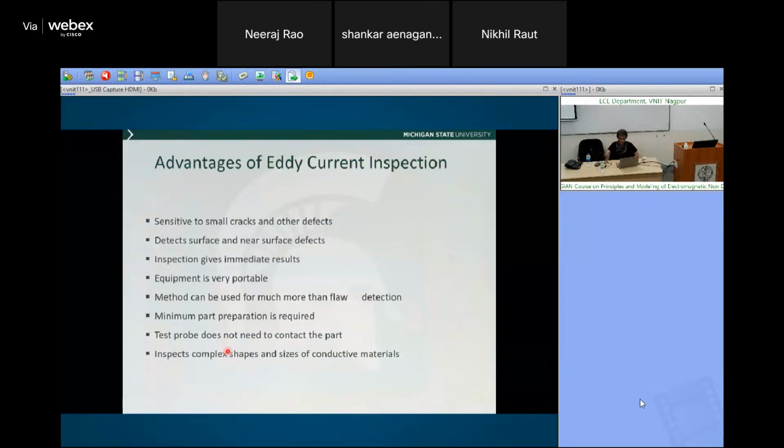The features are, we take 3 different frequencies, and at each frequency we look at the peak magnitude and the phase at the peak magnitude. Simple thing. The neural network is typically 3 layers. We don't go more than that; it's a simple multi-layer perceptron network. But the thing is, we take 3 scan signals and predict for 1 depth, then the next 3 scans and so on. So that produces quite an accurate result.